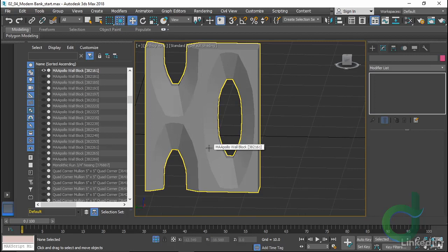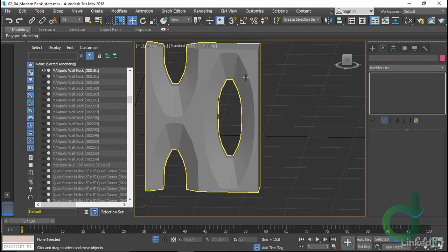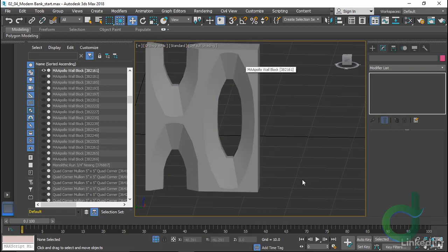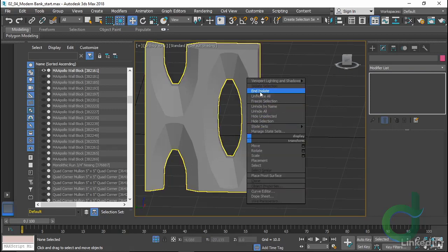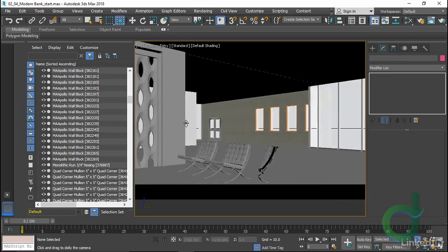Adding in some extra edge lines, although a little bit manual, is a really great way to add in extra geometry versus simply smoothing everything, because that can add a ton of extra geometry if we use a turbo smooth or a subdivision. And in this case, get me just that extra curve to make sure this looks, well, correct per the original. I'll end the isolation, go back to my camera, and check it out, and it looks great. I've got nice curved edges on the sides. This is the kind of model where quite possibly we'll be fairly close.